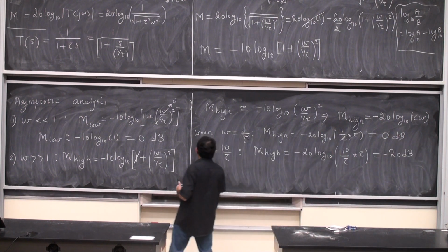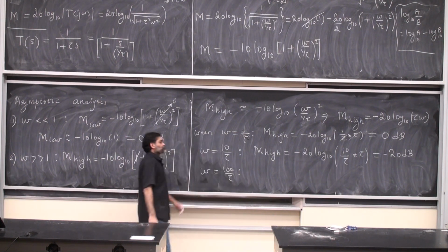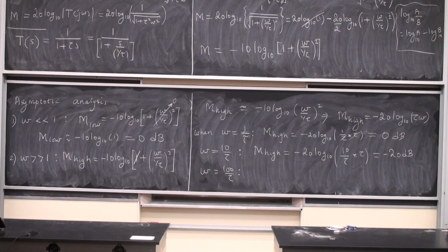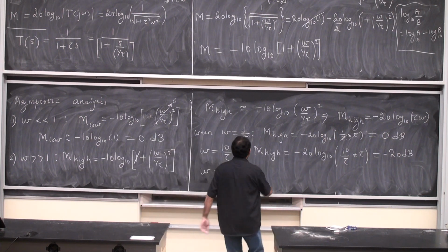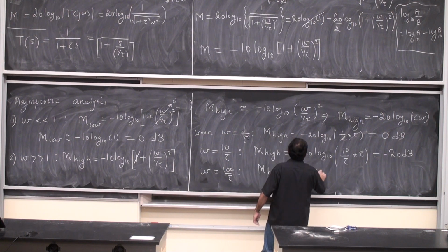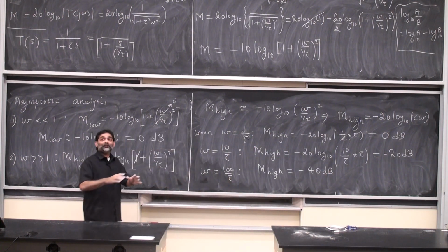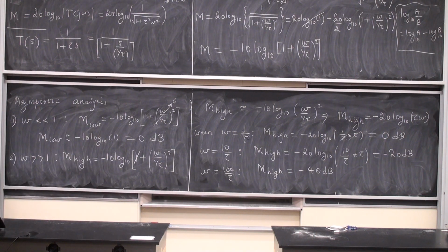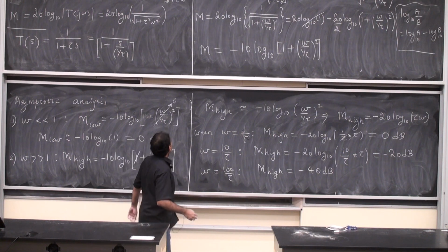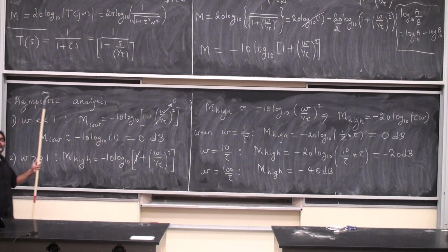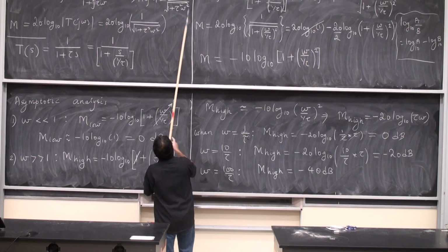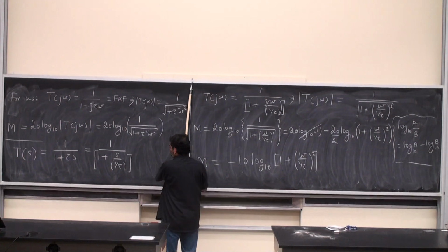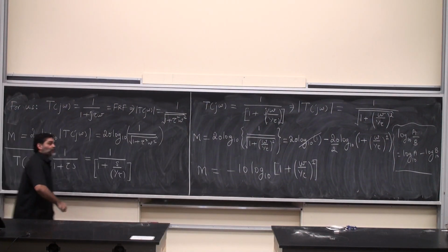As you grow even older, what do you think we should be getting? Minus 40 decibels. And you get the idea, right? If I increase by every decade, I'm going to be dropping down by 20 decibels. And so this is where this equation occurs. And now if I plot it all out, I'm going to wait until everybody has everything before pulling the fan down. I'm pretty sure you've come across this in your electrical systems class. Maybe the same way, maybe a different way. I don't care. Now we plot it all together. And we are not done. There are a couple more subtleties involved.